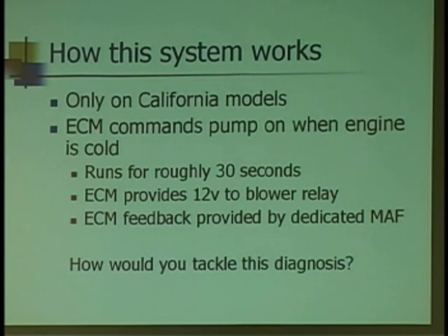So now I know how the system operates. How am I going to diagnose this problem? Right now, there are all kinds of possibilities, aren't there? Relay could be bad, the pump could be bad, the MAF could be bad, could be a restriction in the system. ECM could be bad, wiring, who knows? And I can do it a couple of different ways. I could take out a bidirectional tool and I can start turning the relays on, see if it works, but it's not going to really tell me it works when it's supposed to.